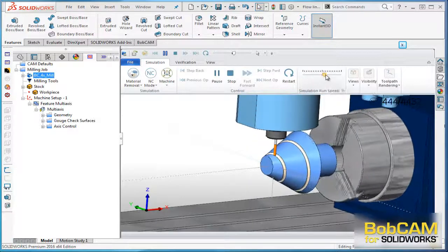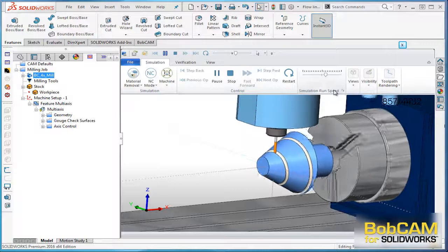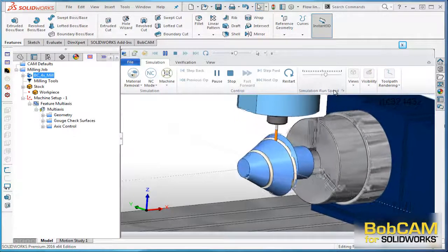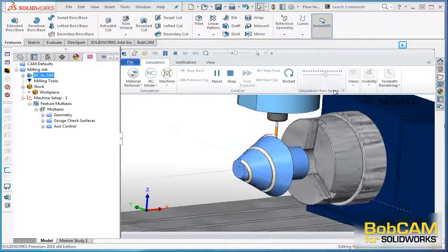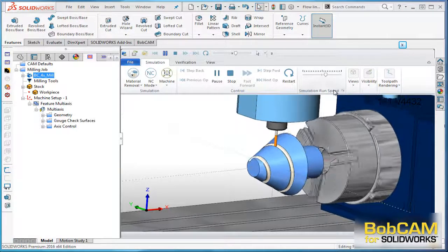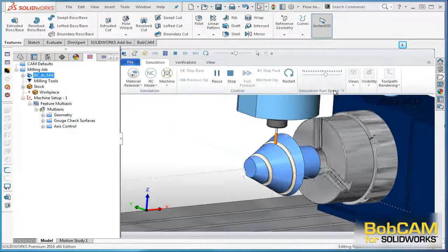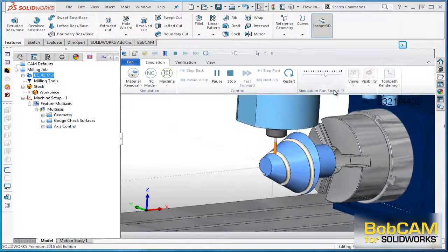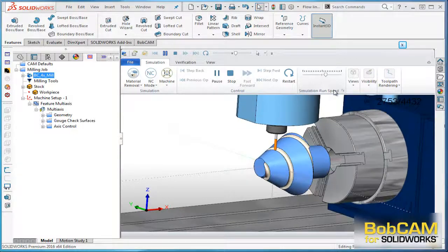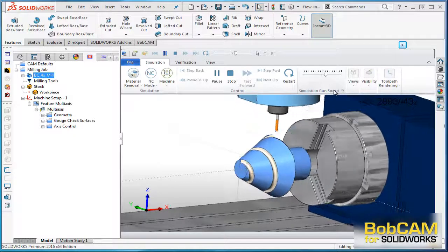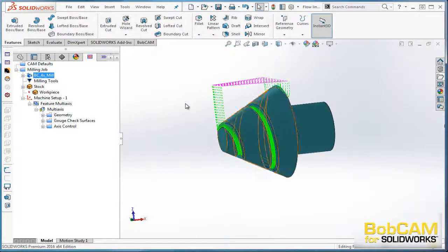It's a very useful strategy because it doesn't require you to use different edges or to blend the surface or to blend the toolpath. It uses the UV lines of your surface to control the direction of cut, and you have 2 directions, either along them or across them. So this is the result that we're getting. So let's go ahead and run through this real quick and see how we set this job up, okay?